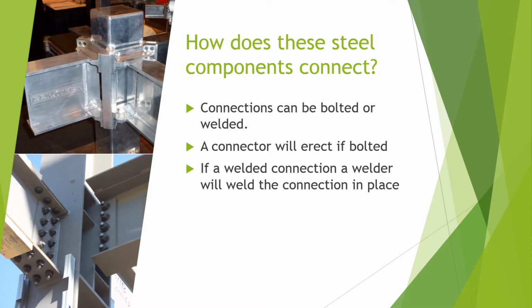So basically you can have two types, and we will see that further on as we do the steel erection course: either how it's to be welded or how it's to be bolted. We have to go by special requirements that are in the notes on our blueprints. So that's how we decide which way that connection goes.